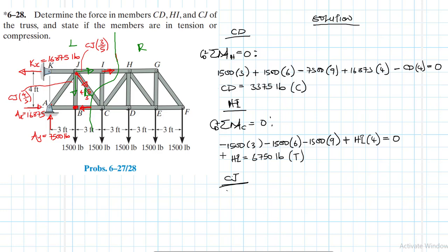All right, so with that information, let's take moments about point B using the left hand section. IC is 0, so we said the force in IC is equal to 0 pounds. This you should remember. So summation of moments about point B is equal to 0. We have a negative CJ going clockwise, 3 over 5 by the lever arm, which is 4.